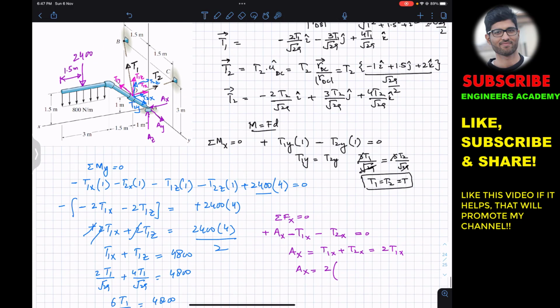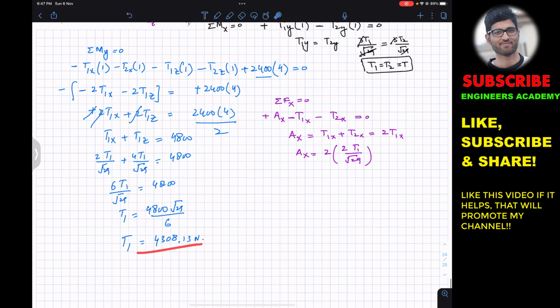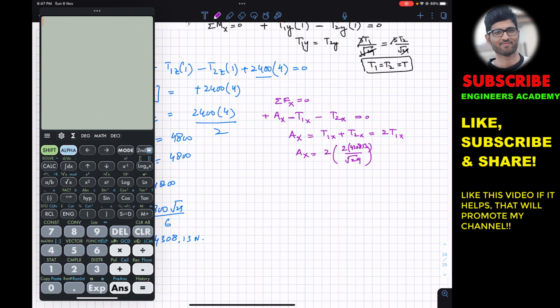The t1x magnitude is 2t1 divided by square root 29, and the t1 magnitude is now known, so we can replace this t1 with 4308.13. So this is 2 into 2 is 4, multiplied by 4308.13 divided by square root 29. This gives me approximately 3200. So Ax is equal to 3200 newtons.